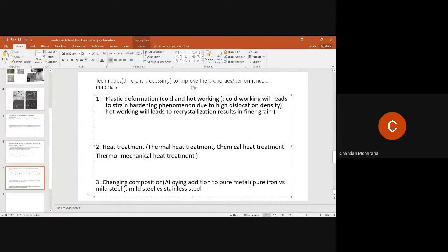What about stainless steel, I mean chromium and nickel? Substitutional. So which kind of strengthening will be there? Substitutional strengthening or solid solution strengthening. It forms a solid solution. Do you remember these things from physical metallurgy? So we form a solid solution. Solid solution always increases the strength of a material due to elastic strain in the body. Okay, fine. So you understand.